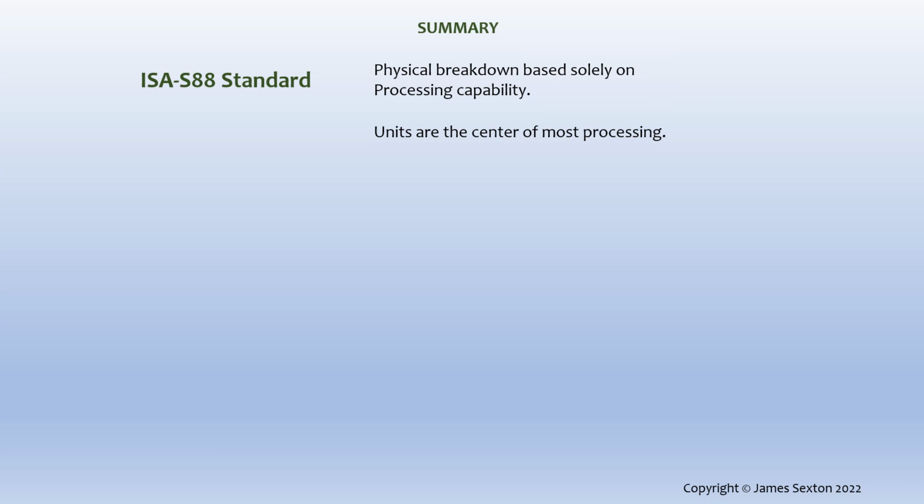The original version of ISA-88 identified only two examples of equipment modules: dosing equipment and weighing equipment. It's hard to think of many other processing activities that are done outside of units. Perhaps some forms of filtration, separation, or decanting would be considered minor processing activities and qualify. Some industries may have more candidates than others.